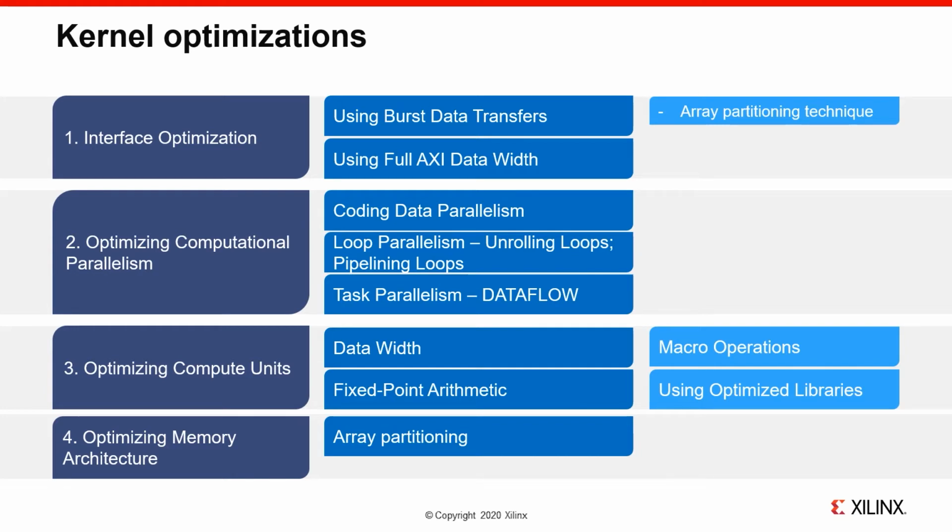Data widths or data types should be reviewed and matched to higher level interfaces to maximize bandwidth. FPGAs are not restricted to standard data types and can implement custom precision arithmetic. Lower precision custom data types reduce on-chip and off-chip storage requirements and reduce the size of the data path operators we need. We can use system bandwidth more effectively if we only need to move these smaller data types, and we can save FPGA resources by using smaller operators.